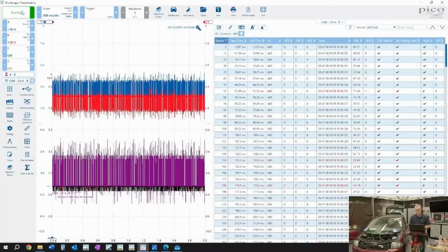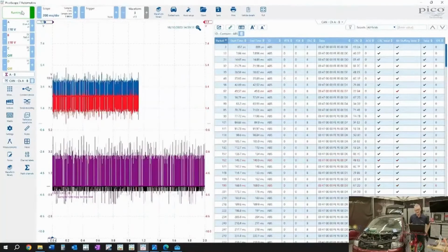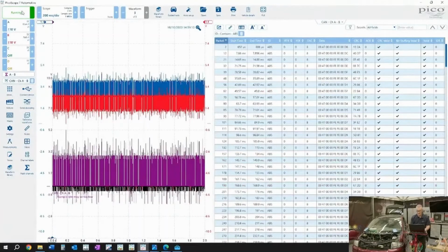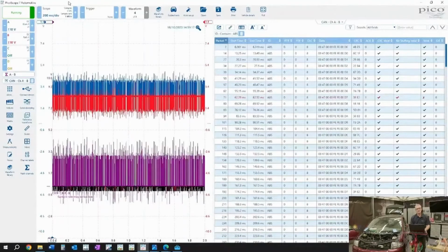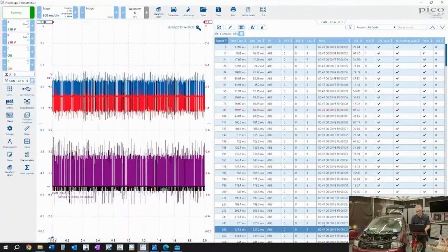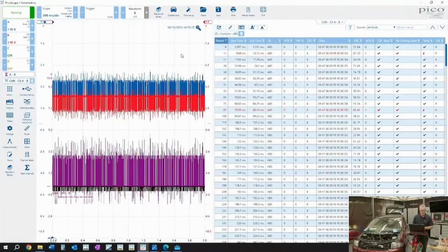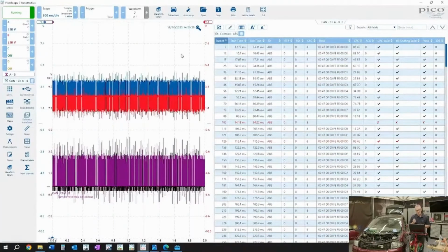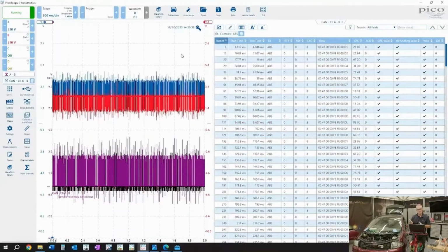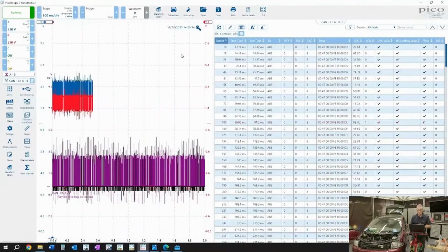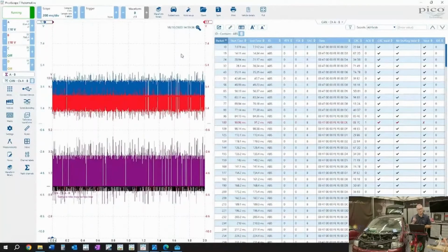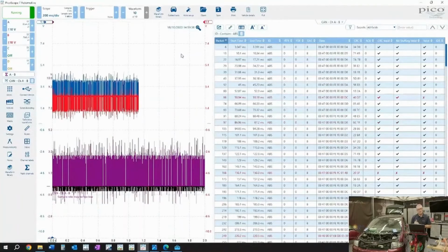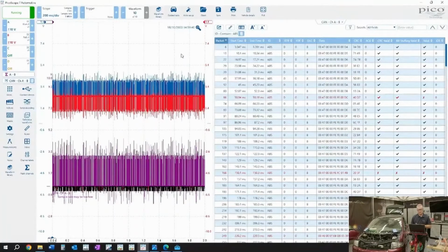Which then brings me on to the data packets. Now, just note that in the data field, we have 0047, and it's that second byte that I wanted you to keep an eye on, because the plan is now to actually press the brake pedal, because I know either through reverse engineering or DBC that byte 2, by changing one digit, actually represents brake pedal position on or off.